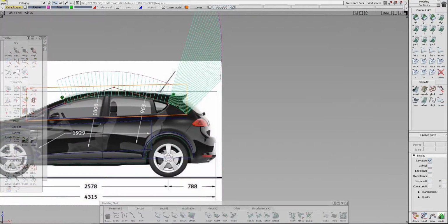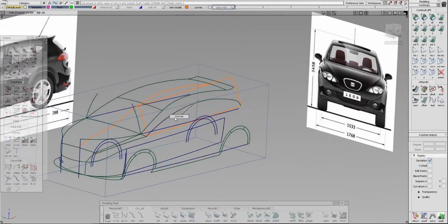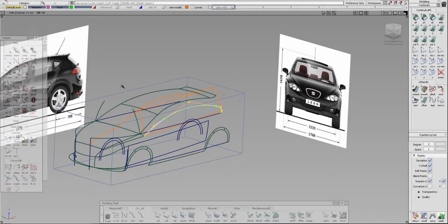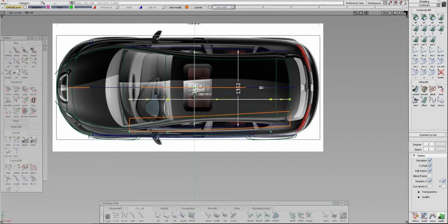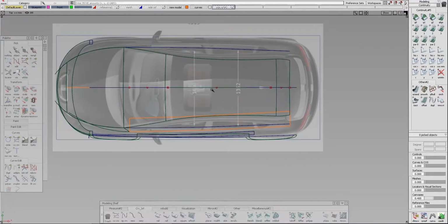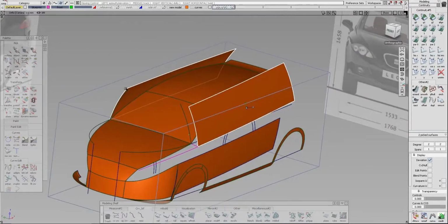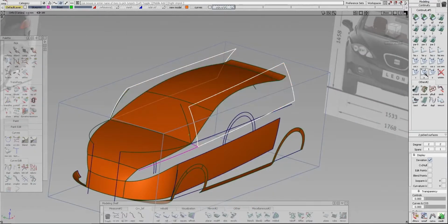Okay, so I'm just playing around with the shape of it, getting something that I like. Okay, so now I put the points on and select all the CVs and snap them to the grid and move them to the center. And that way I planarized all of those curves, and I'll make the blueprint a bit more transparent so that you can see it better. Right. So there's our side glass surface, and now we can project onto these surfaces the curves that we've just built.